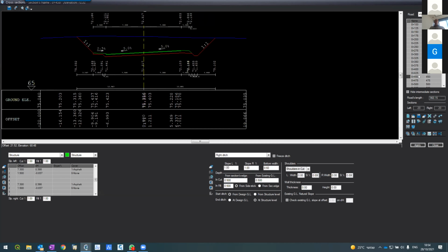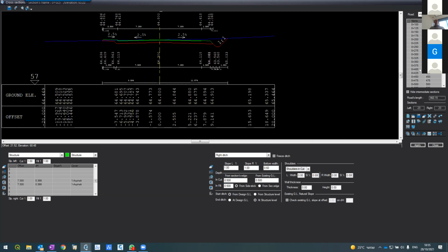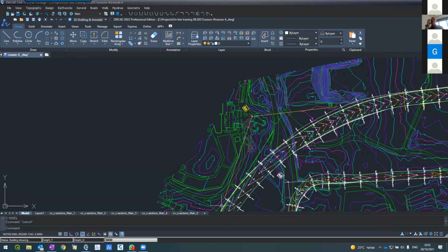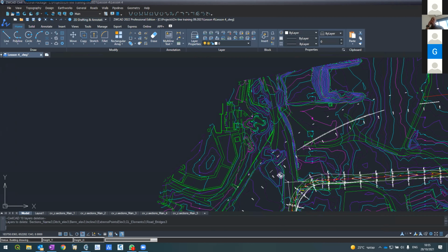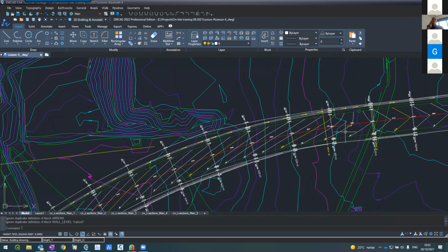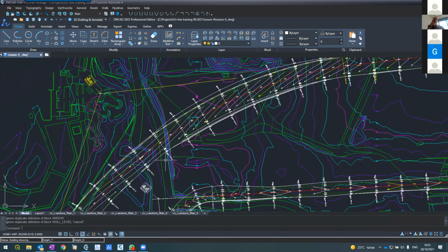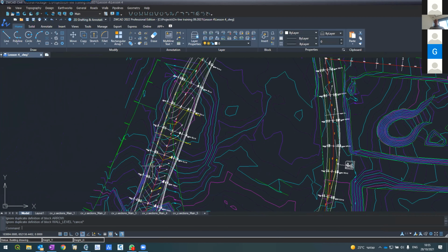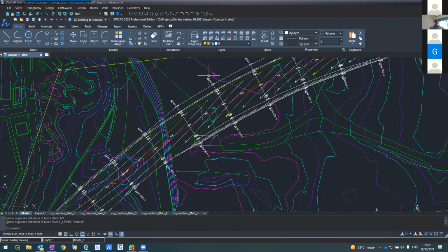By the way, I saw something interesting. Okay, let's leave it like this. And now let's recalculate the layout. Now we're supposed to see the transition here in the design elevation, the design contour. So here it is. Okay, excellent. From here, we're transitioning into a full one-sided slope, again here, and transition again to the left. That's it. This is how I created the super elevation.